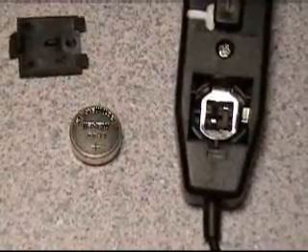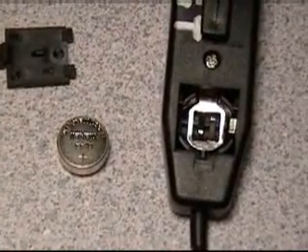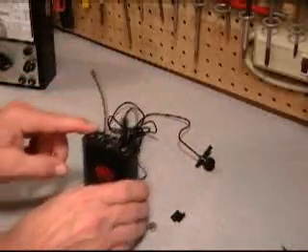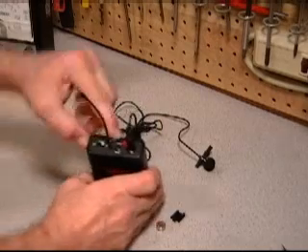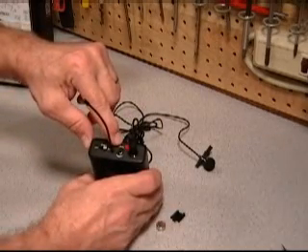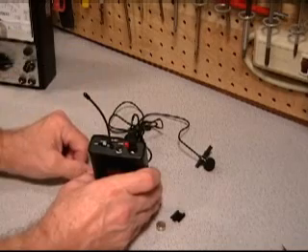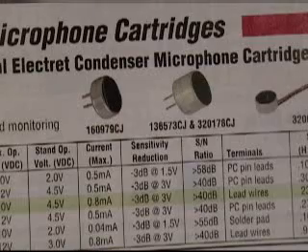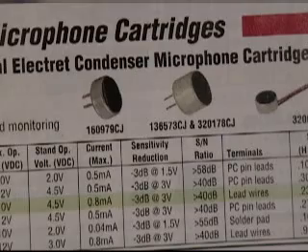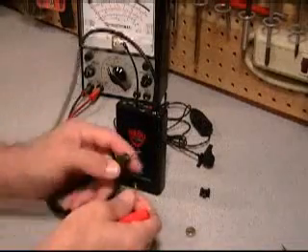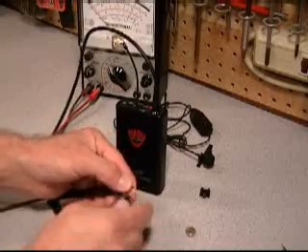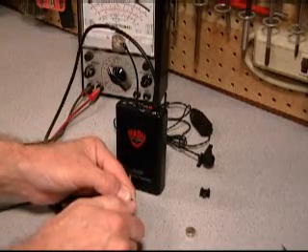The microphones require a 1.5 volt button cell battery. Now the wireless packs and the lavaliers were working good, but the audio level was a bit low. Even with the transmitter pack's gain turned all the way up, a slight hiss could be heard. Most of the low voltage condenser microphones will perform better when the voltage is increased. I tested the Nady pack and found that there was 9 volts on the microphone connector just waiting to power a condenser microphone.